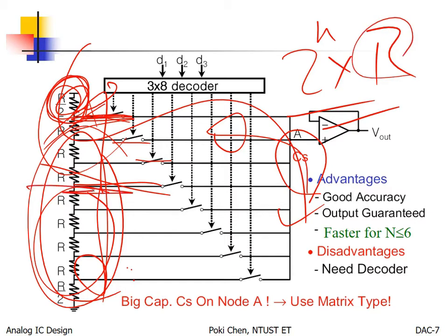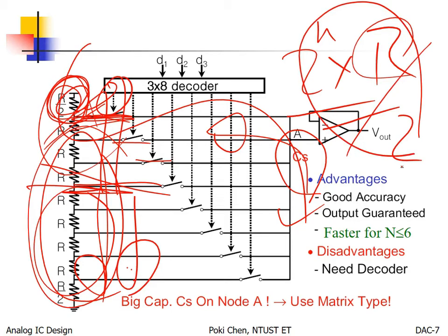So in the middle, to the top, to the bottom, they are all the same divided by 2. And those 2 equivalent resistors will be in parallel, so divided by another 2. That is the equivalent resistance for the worst case.